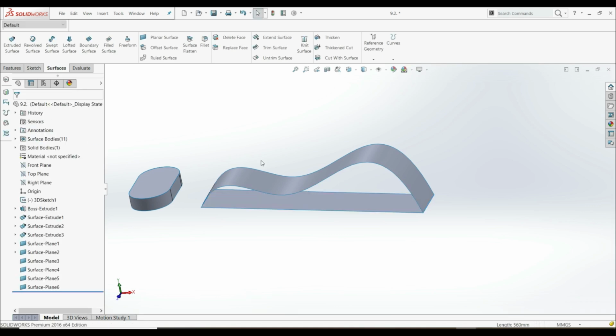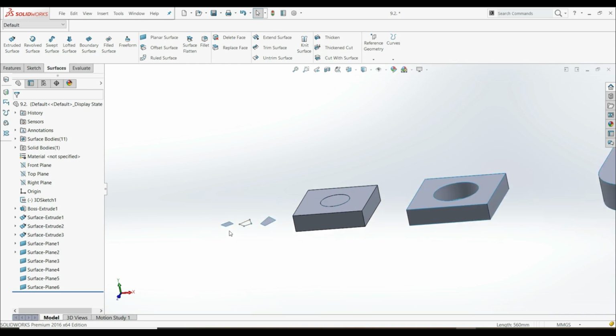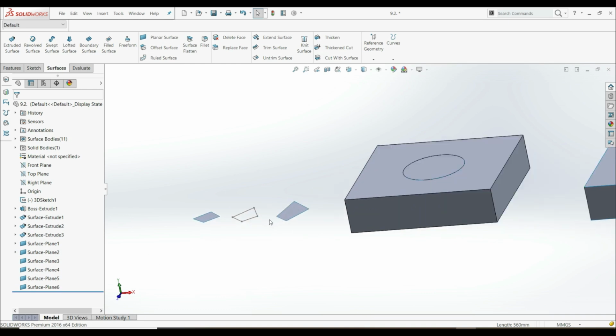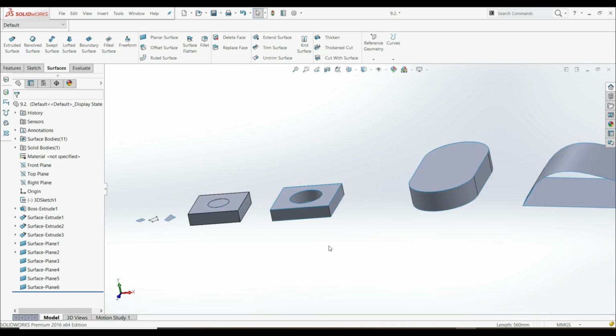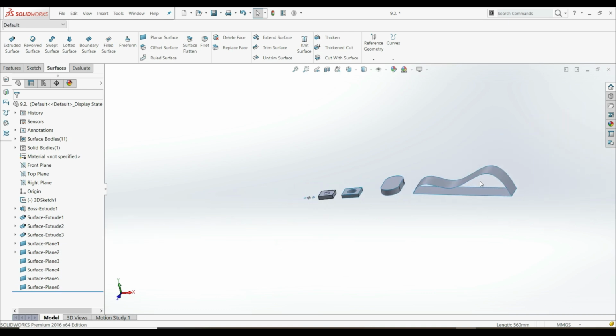Let's click OK. So this is a straightforward tool to fill some patch or hole. Remember, for the sketches, it must be a 2D sketch and you must have a closed contour. But for the surfaces and parts, you don't always need a closed contour. Sometimes it works when you have an open contour, as we have seen here and here, and as we see here.